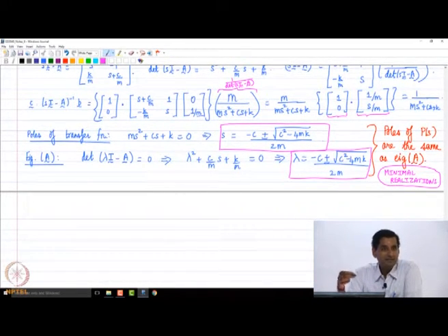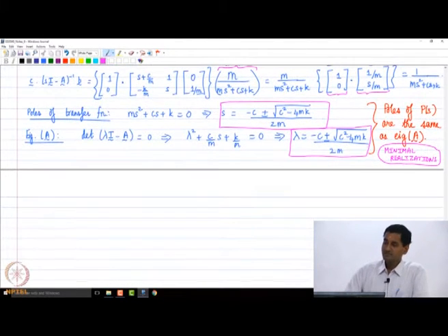So the task of ensuring asymptotic stability boils down to the location of the poles of the transfer function or the eigenvalues of the state matrix. Okay, so that's the equivalence which I wanted to show you here. Is it clear what was the purpose behind this particular derivation, right? Of course we can go deeper and deeper, but I am not going to do that here because our course is mainly focused on transfer function based analysis. But I just wanted to give you an introduction to state space, and we would learn more about this in an advanced course on controls, right?